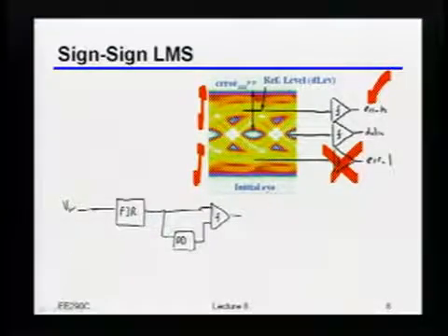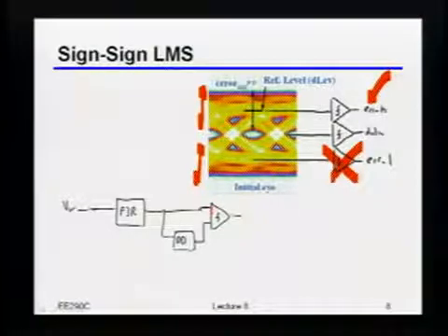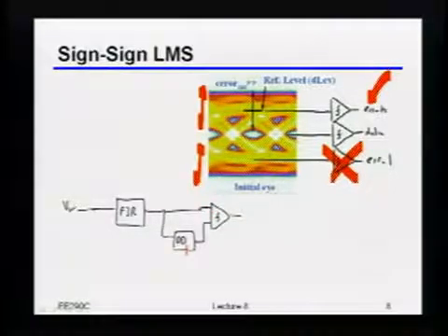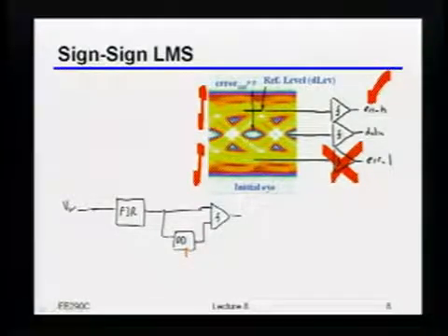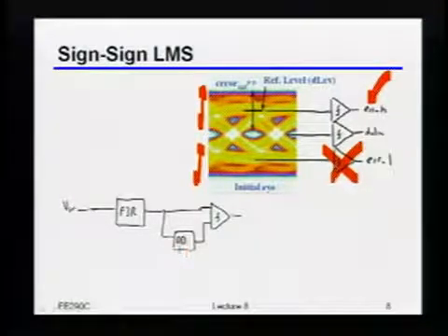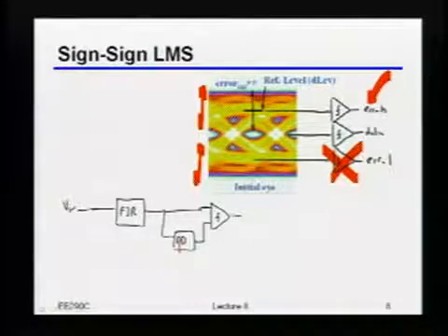Let's say that I want to get this right to within 100 microvolts. Tough, right? I have to build a really, really good peak detector, right? Maybe it can be done, but tends to be kind of tough, okay? And by the way, I just added some extra loading and stuff onto my high-speed signal path, which, okay, maybe is not horrible, but there's another trick you can play.